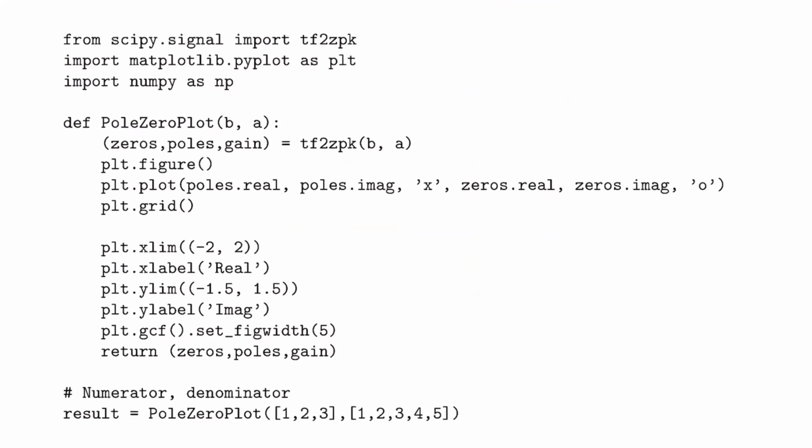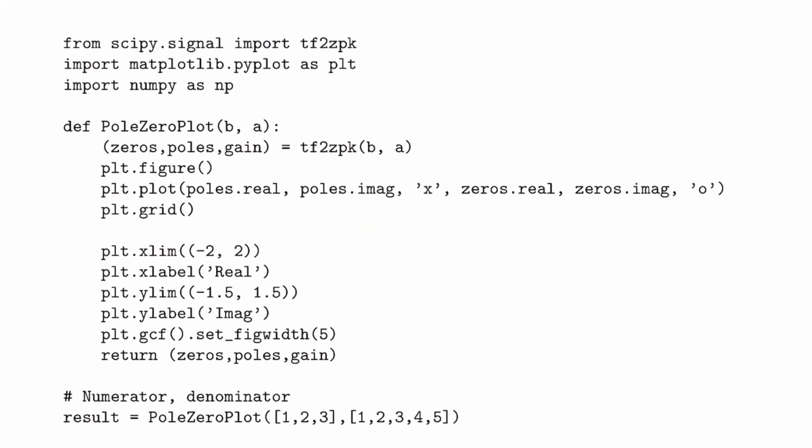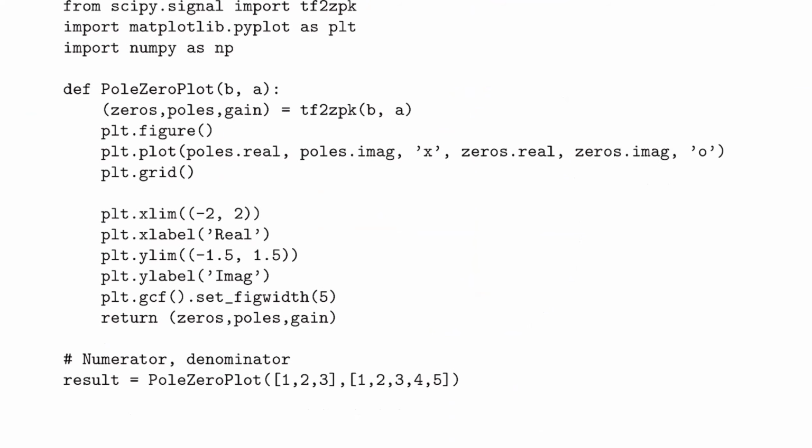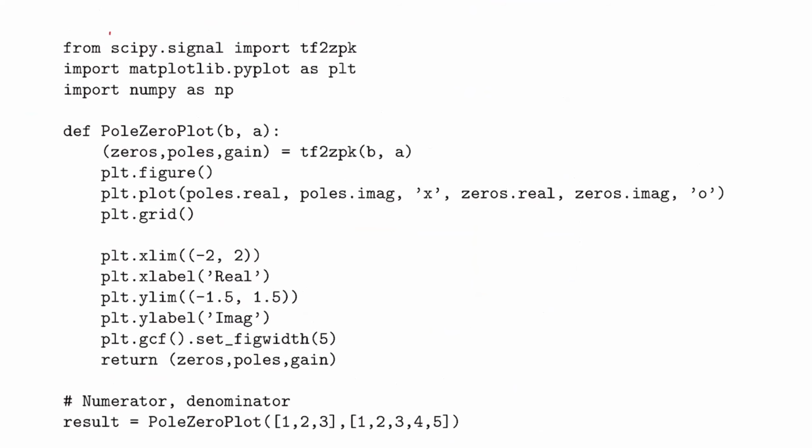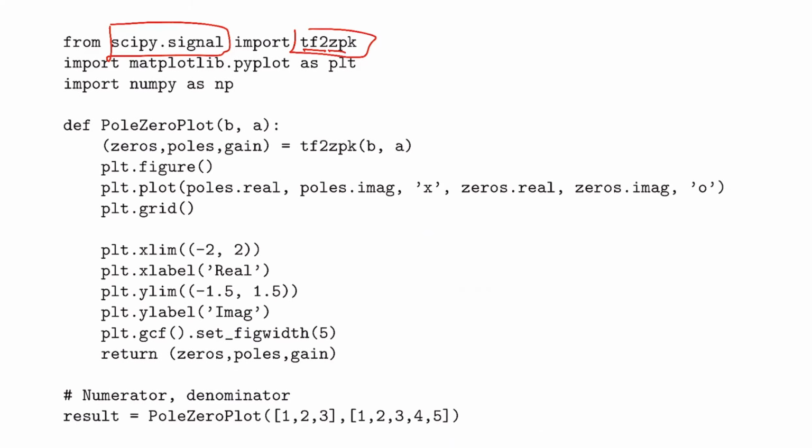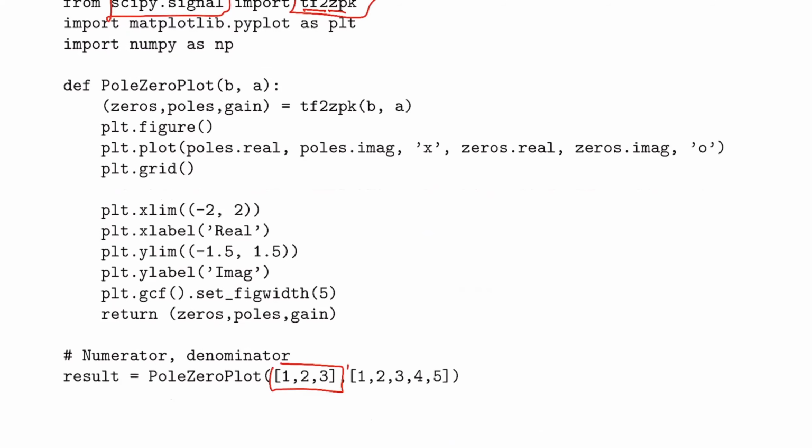I came across some software that you can use in Python to compute this, and I will demo this on Tuesday. That you can use to plot. It's pretty simple. There's a SciPy signal package that has this function called tf2zpk, oddly named thing, but it stands for transfer function to zeros and poles. There you go, right? Transfer function to zeros and poles. What you have to do is you have to give it the coefficients of the terms in the polynomials in the numerator and the denominator.